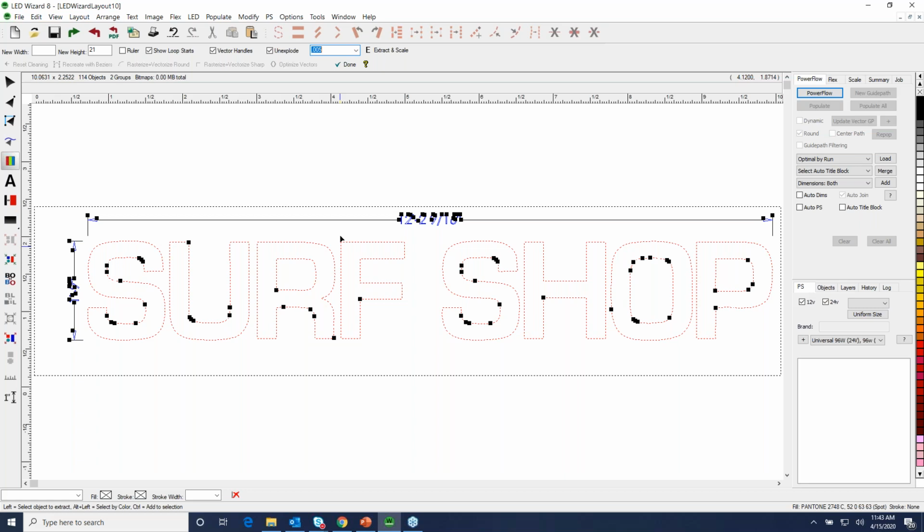A lot of times these files have the points that are coincident. They're right on top of each other. This one's not quite as clean, but I tested it before, and 0.005 is big enough to capture and connect most of these. Okay, you don't want too big of a value because then it gets a little bit crazy. So you want the smallest value that works.